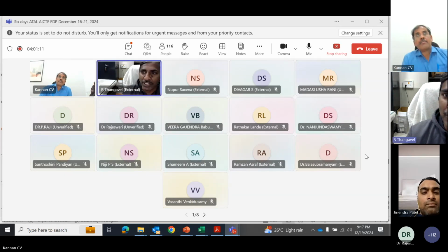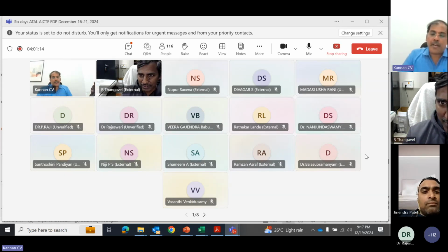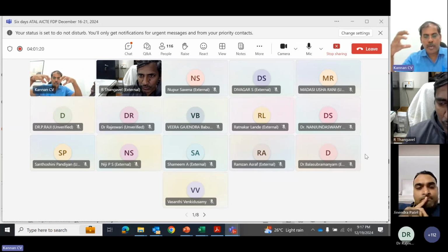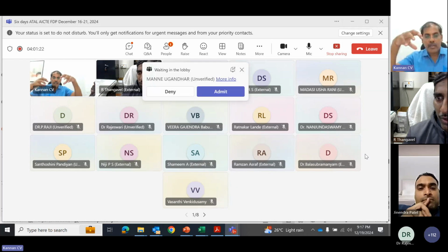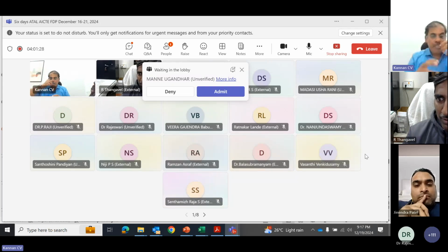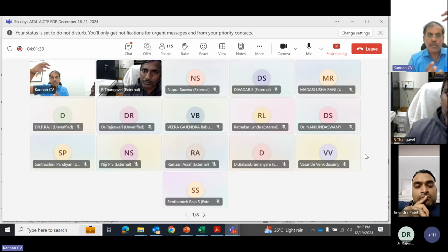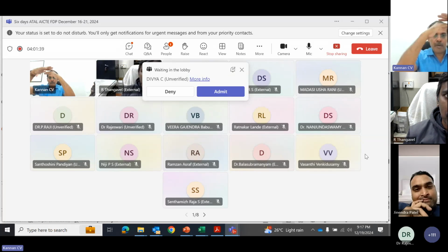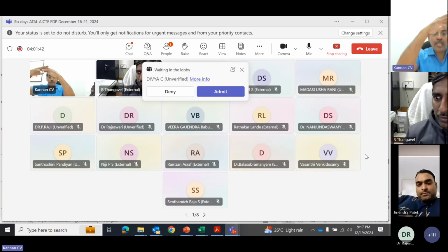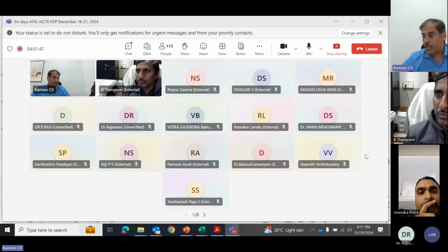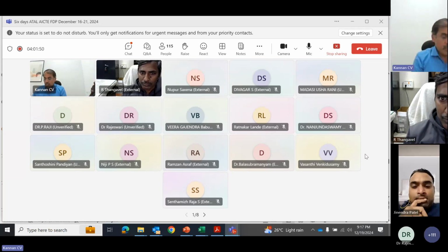See, electrical conductivity, normally we define it when pure polysilicon is used, by the amount of dopant material we add. Based on the growth process, the pulling process, and the segregation coefficient, we know how much dopant will go into the crystal at every stage of growth. Knowing that amount, we know what the resistivity would be, because once dopant goes into pure silicon, the resistivity changes.